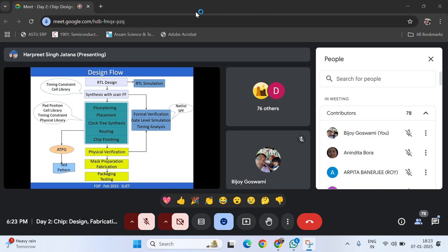And once you have done the synthesis, and finally it shows in terms of various gates and flip-flops, then you will decide the floor planning, which is a very important part. Like in a house, where you do the bedroom, where you do the kitchen and things like that. There are certain guidelines for doing that. Like if there is a very rapidly changing, very high speed signal, that circuitry has to be properly guarded, and it should be away from any low noise analog signal.